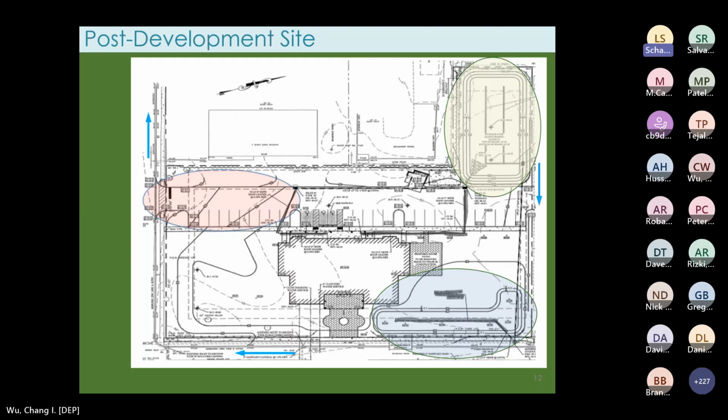All right, the system then flows west under the roadway on the left side of the property. Back up the page, okay? Now, the red oval is a portion of the parking lot that discharges to the south, where it would enter that MS4 system in the roadway, but it's doing so without any treatment for water quality or quantity control. So this project does not comply with the design and performance standards.